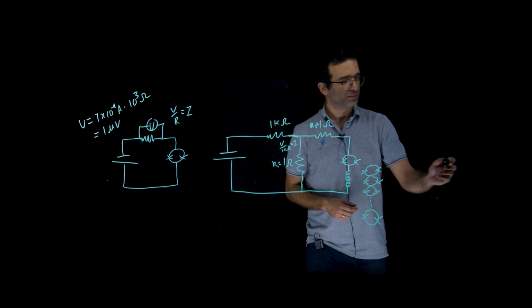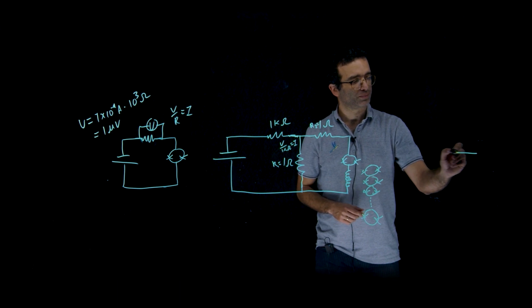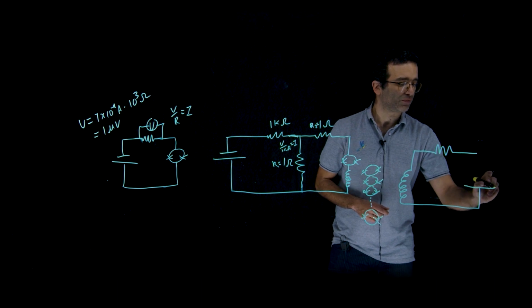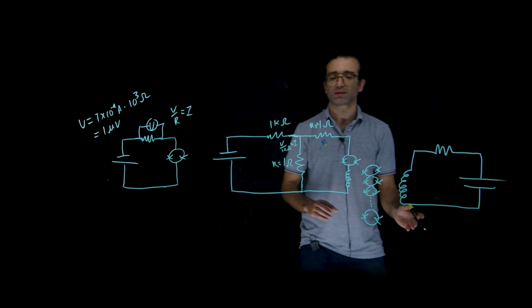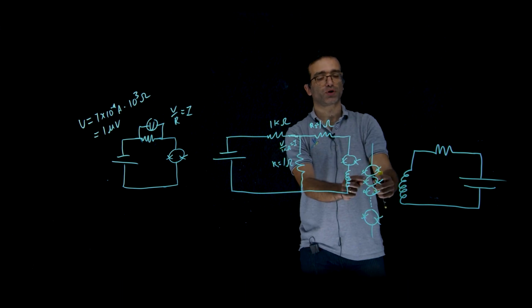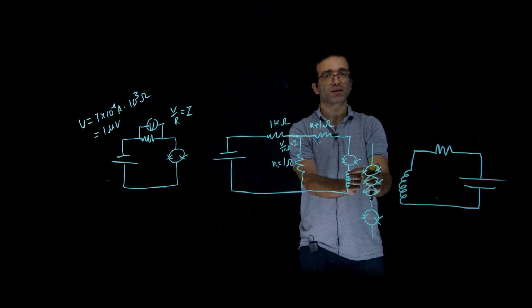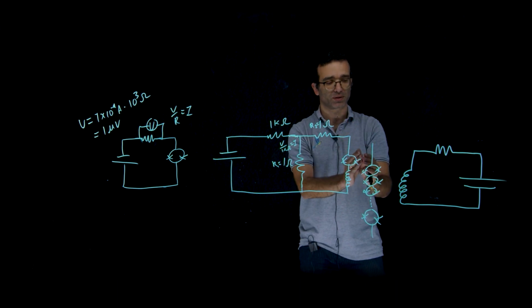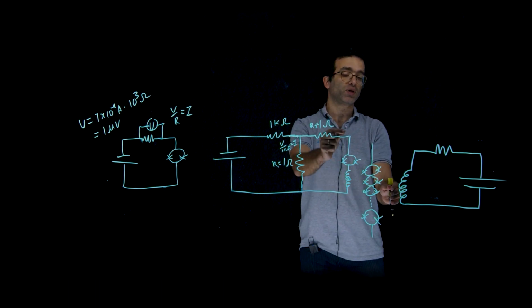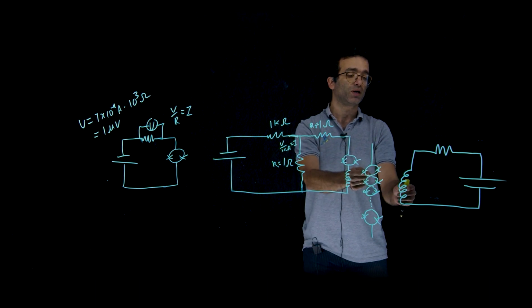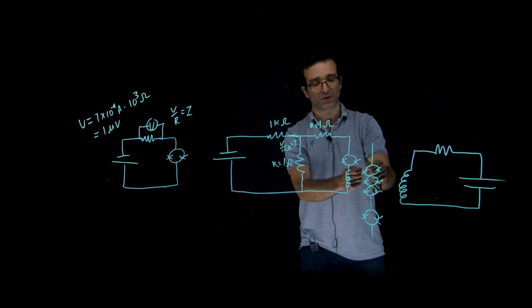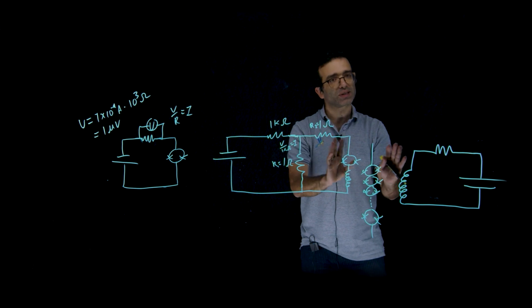And on the other side, you have another circuit with another coil, and you build some electronics that reads the voltage here that is proportional to the flux and tries to keep the flux on the SQUID constant. So basically, if you increase a bit the current here, you increase the field here, so this guy will try to compensate for that by creating an opposite field.